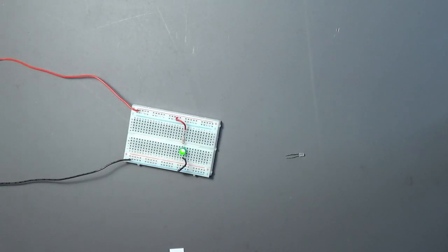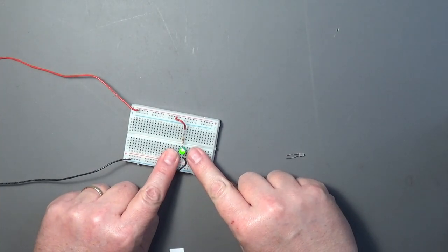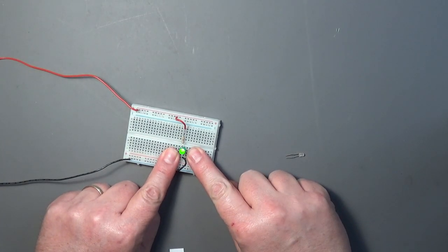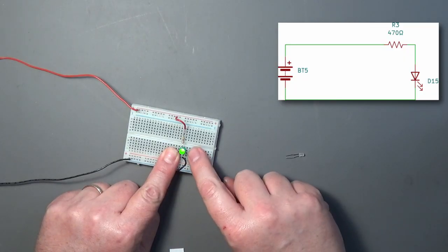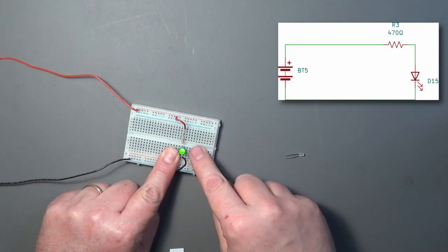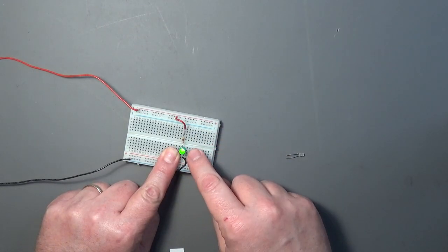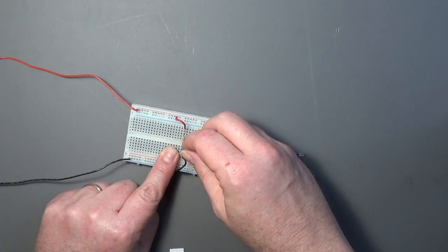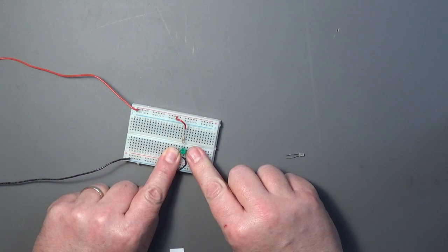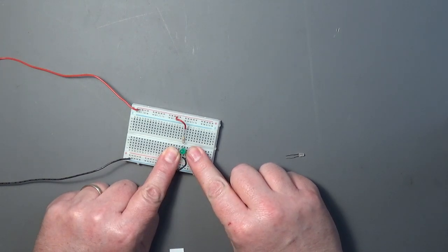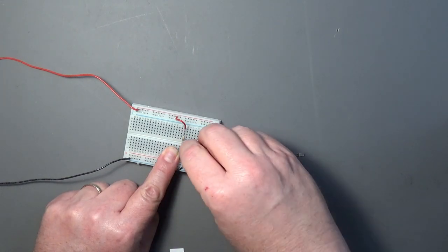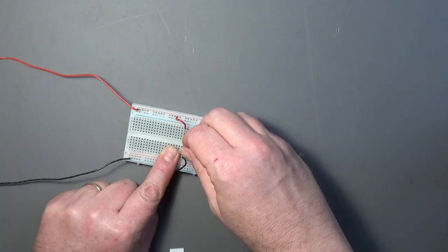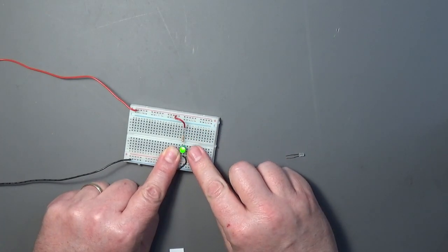A very common type of diode, and one we encounter in everyday life quite frequently, is the light emitting diode, or LED. So I've got one right here. That must be a green one. It works just like a regular diode. This one's currently forward biased, and so as it's forward biased, electricity goes through it, it emits light. If I take this one and flip it around so it's reverse biased, it doesn't turn on because it's a diode and it won't let electricity go through backwards. Turn it back around again, and forward bias, we turn on again.